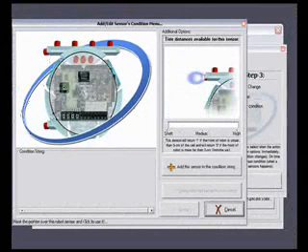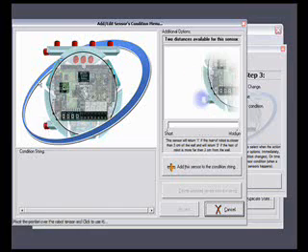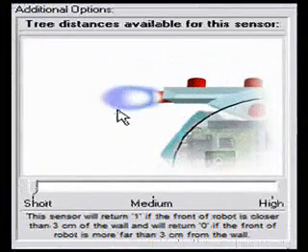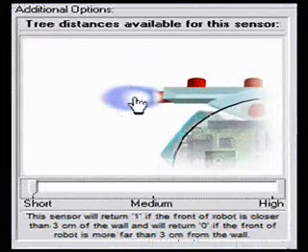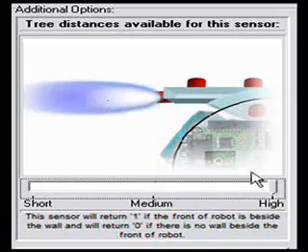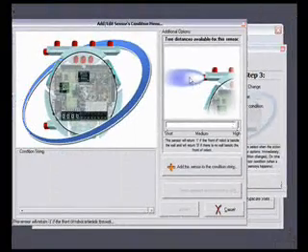The wall sensor is used to distinguish if there is a wall or not and how far or how close the robot is to the wall. It has 3 wall sensors up front. The closest is used to indicate that it is less than 3 centimeters from the wall. The one in the center is used to indicate that it is located at least 6 centimeters from the wall, and the farthest is used to indicate if the robot is next to a wall or on a curve.